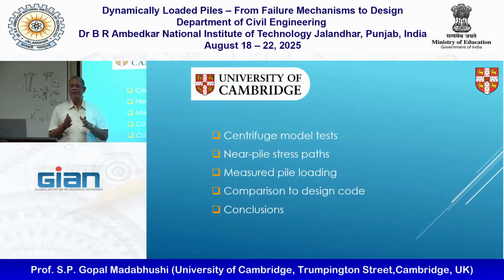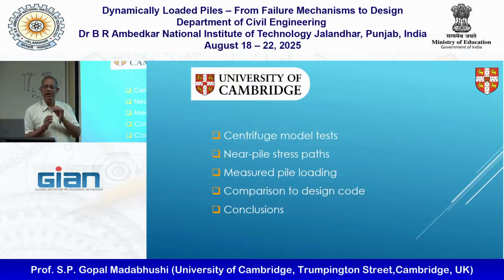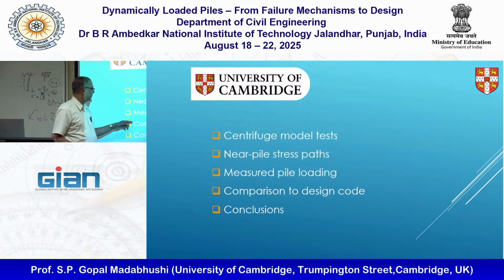We tried to do this using miniature pressure cells. Nobody believes earth pressure cells, or you should not put all your money onto earth pressure cells. Earth pressure measurement is one of the hardest things to do in soil mechanics. So we also had bending moment strain gauges on the piles to measure bending moment and the pile loads.